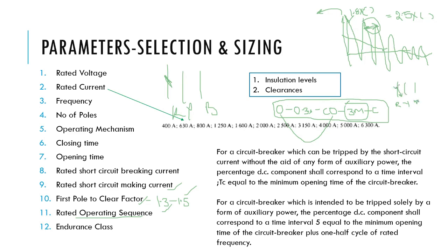So the breaker, seeing this, opens here, but it checks some conditions that I will talk about in the control and protection chapter. If the auto reclosure function is enabled, it takes some time, which is 0.3 seconds, and again I forcefully close the breaker.